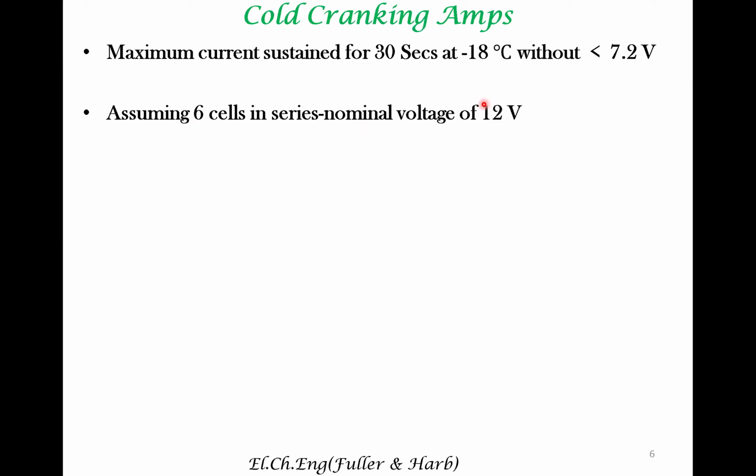So the typical voltage can be about 12. That's when we saw the nominal voltage in the previous slide of 2 volts. That is from a single cell. 6 times 2 volts gives you 12 volts from a battery. Here, you cannot go below 7.2 volt.